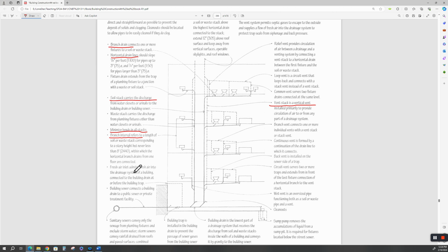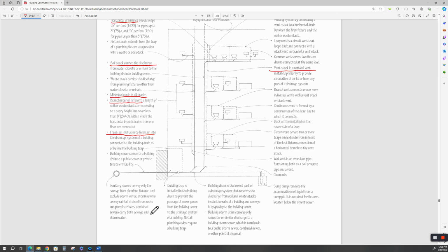All right. And then you're going to want a fresh air inlet down here at the bottom. This is like for a commercial building. It's just a fancy name for a vent stack for your main sewer that goes out to the sanitary sewer. Okay. And all of this is gravity fed. All right. So you've got to watch your slope. You've got minimum slopes and you've got maximum slopes. If the slope is too great, then the toilet paper and those quote-unquote flushable wipes and the solids will start to, the water will run ahead and leave the solids back in here, and you don't want that.